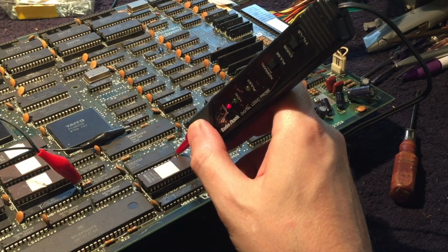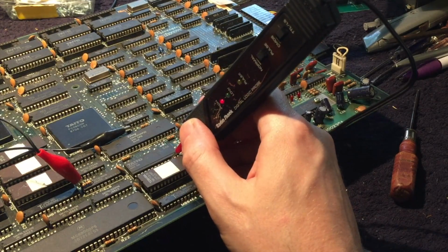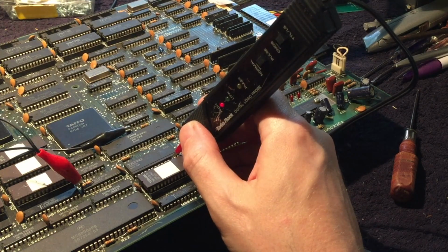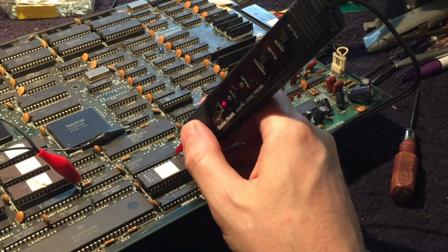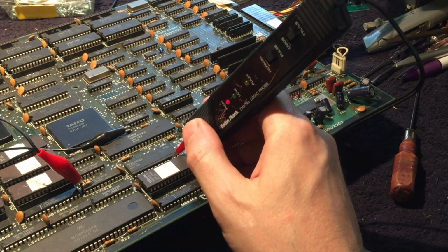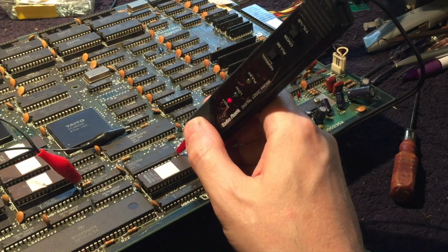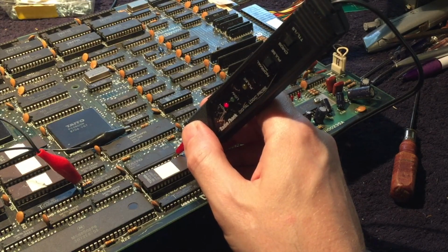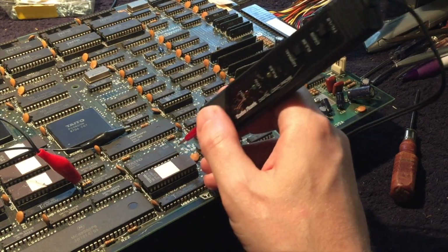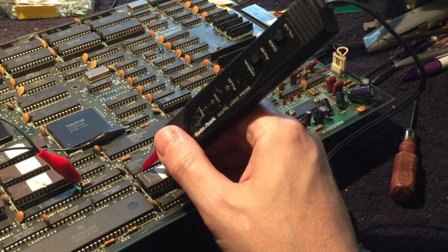So that's actually mildly encouraging, because we're getting as far as from the main CPU to the other side of the custom chip. Now that doesn't mean that nothing else is broken on this custom chip, but it's at least encouraging that the NMI is doing something. Let's see if this Z80 is trying to read this guy at all.